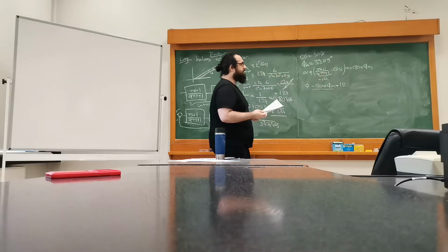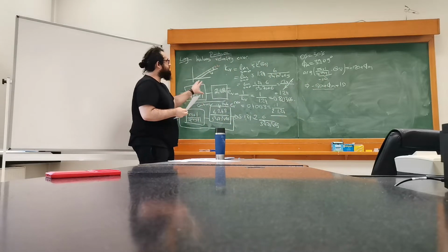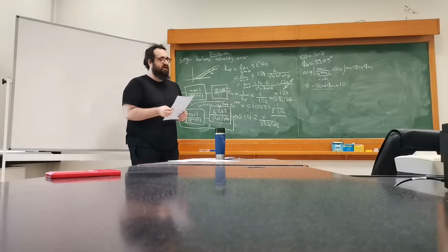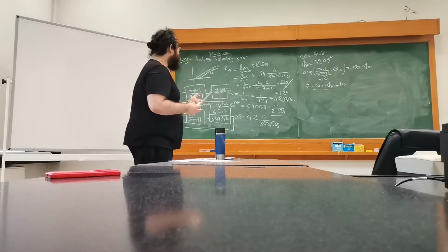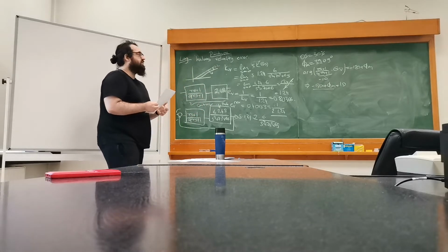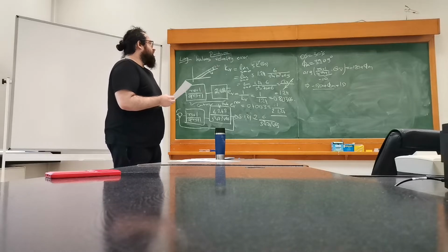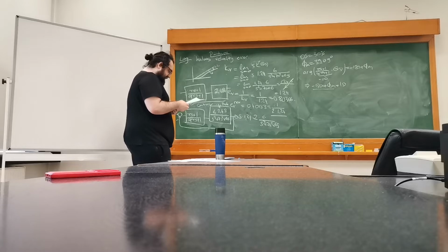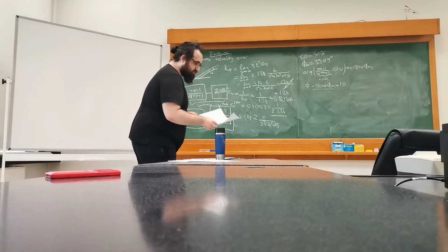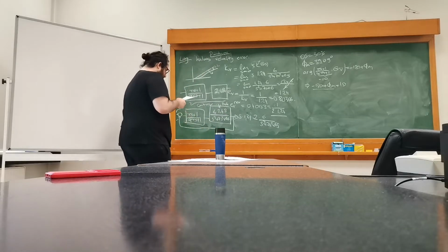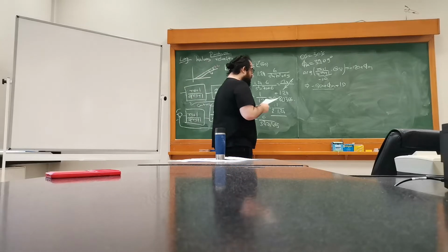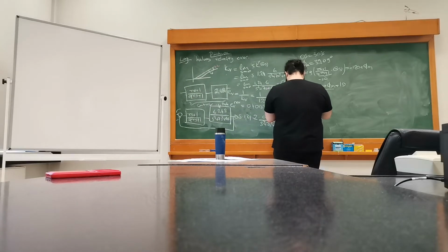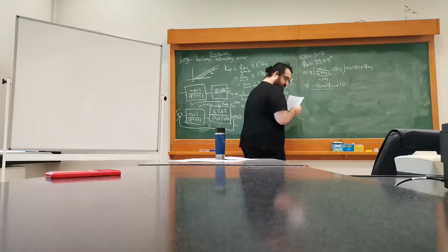So that's really important. Because the lag controller does not try to update the transients or change the behavior. It tries to update the steady state behavior, as in this case, and not affect the transients of the system. So that's why we have to add 10 degrees. So once we've done that, we're basically searching for, let me see, did I write it down?